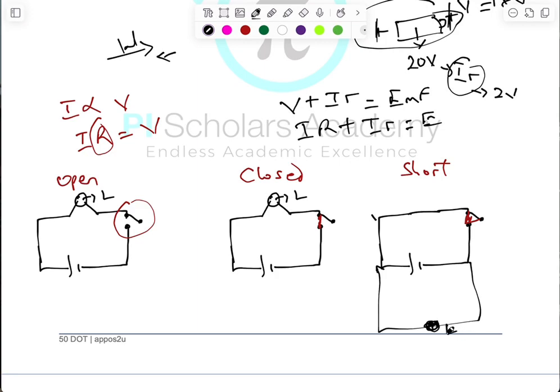This is the load. Of course, like I said, resistance is opposition to the flow of current, so this load is going to offer a resistance. But when you look at the wire that you have here, there's no load in this place. So the current has two options, either to go this way or to go this way. If it goes down like this, it's going to power the load, but with high resistance. If it goes up now, it's going to be with low resistance. So current likes to travel through the path of low resistance, so it goes this way instead. And it can cause this to be damaged. There can be a spark, there can be overheating, and different things like that. And this load will not be powered in that system.